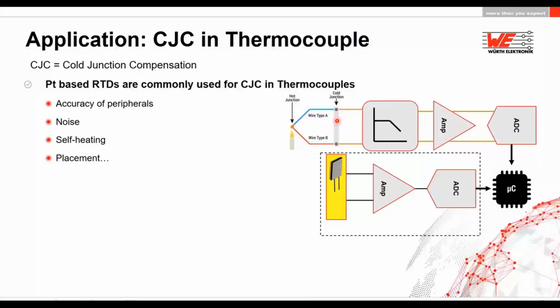So here, when you say that my sensor has an accuracy of X percent, you then also add some peripheral devices, for example filters and amplifiers, which add some noise and also add inaccuracy to your complete system. So at the end, sometimes you have to recalibrate your whole system. The RTDs also might have a problem of self-heating, and they are very design sensitive. So you have to take care of your design and invest a lot of time designing complex circuits.